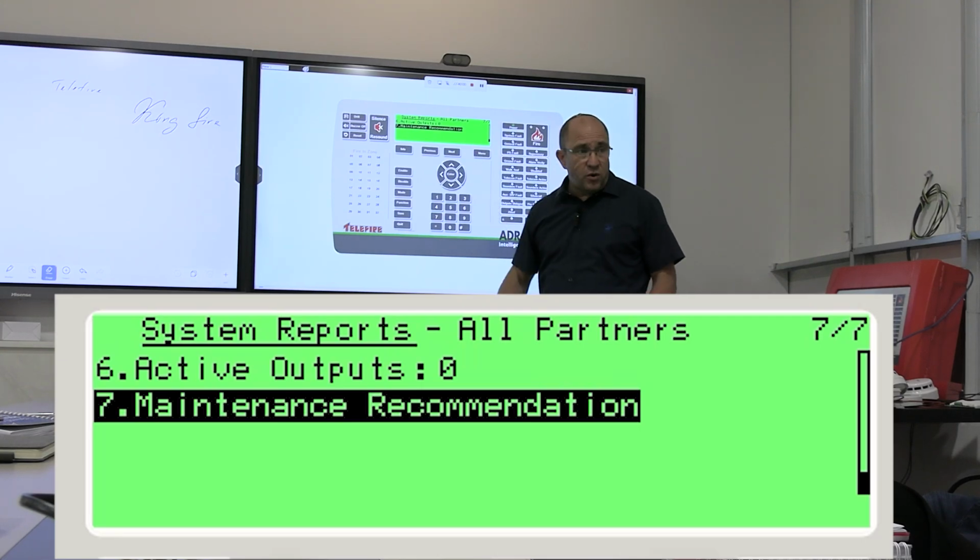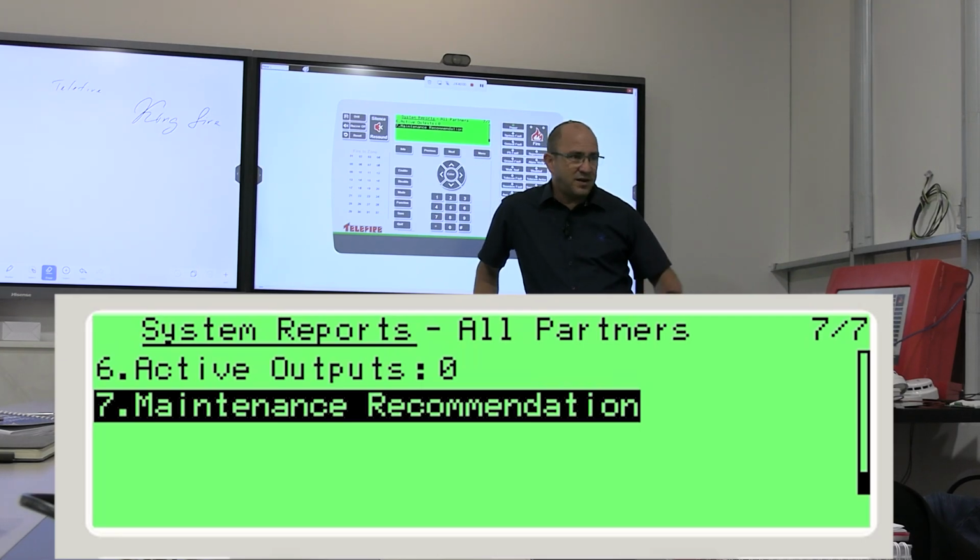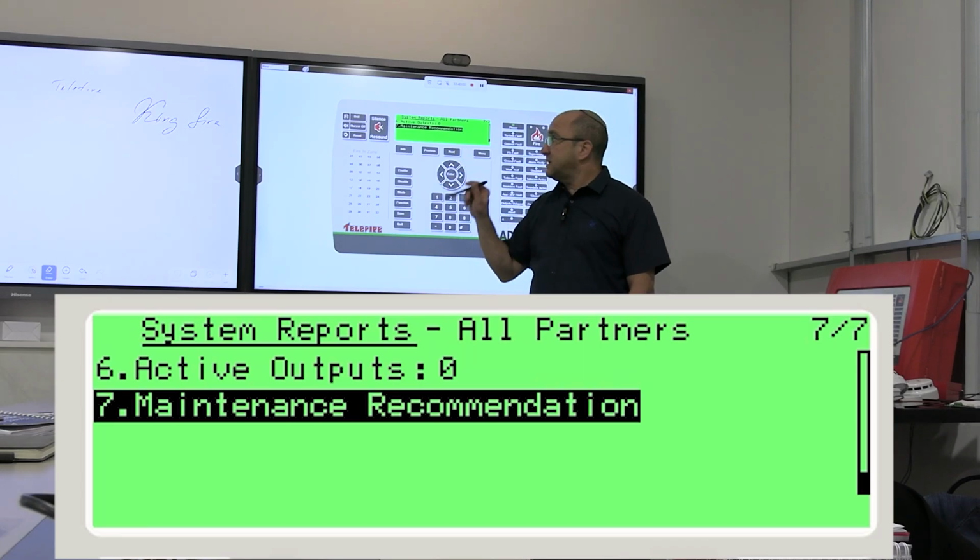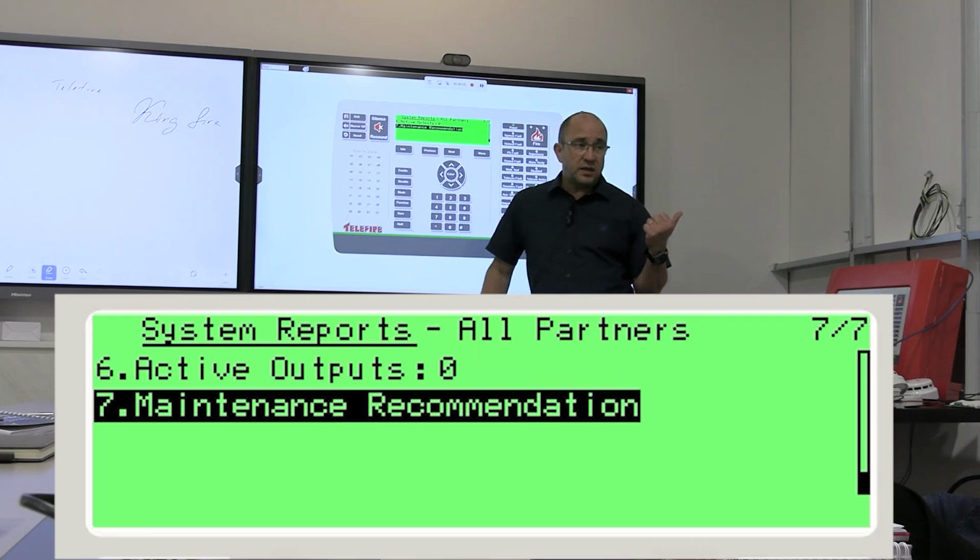If this is 0, it means the card didn't get a command to activate the output. If it was 1 or 2 or 3 or 5 or 6 and I scroll and I see elevator go down, oh, there's a problem. The card got a command. Now I must put on the hat of a technician, take my 3 friends. Who's the technician's 3 friends?